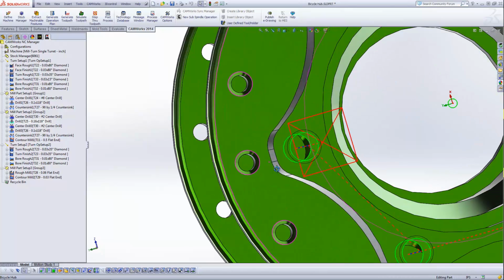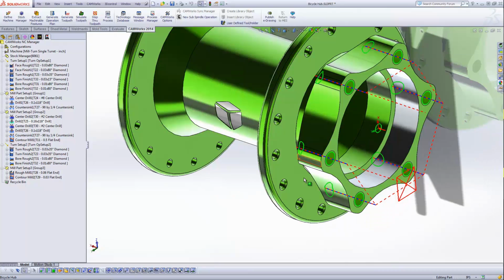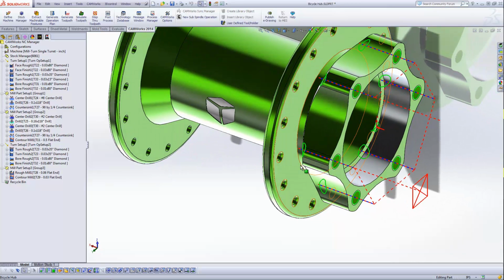I was slightly gouging over here, so that's a matter of tool choice. I'm maybe running a little bit low on time, so I don't know if I'm going to address that, but that's a good way of knowing that the shank of my tool is too large, so I need to narrow that down a bit.